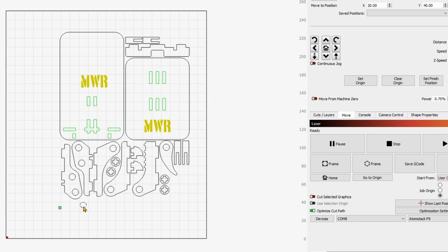And so what I can do is I can either jog, you know, to try to figure out where it is, or if I have a grid, and that's something that I normally suggest, to fix the workpiece to a board and to let the machine engrave it on grid, so you will have a fixed reference point there.